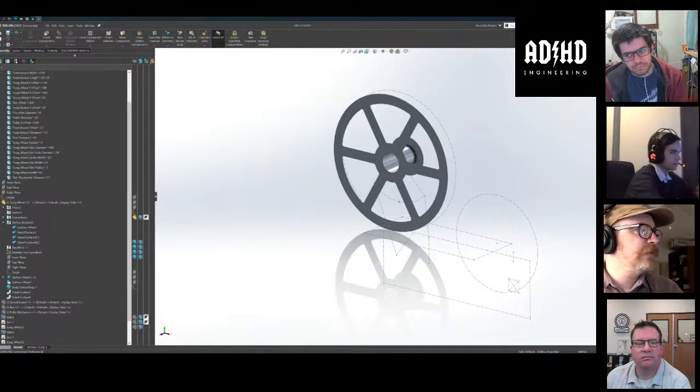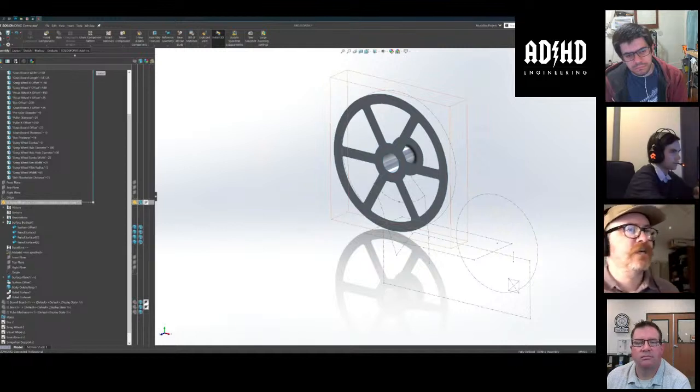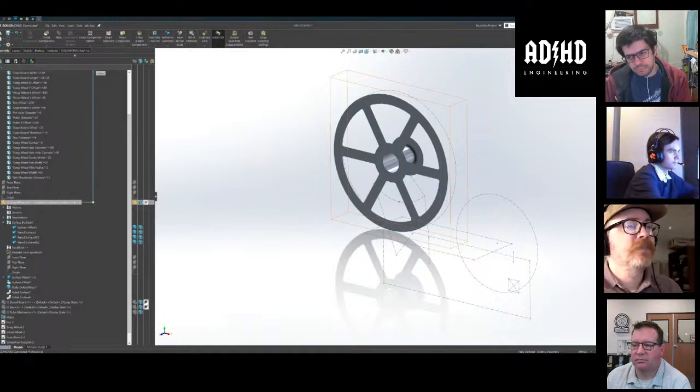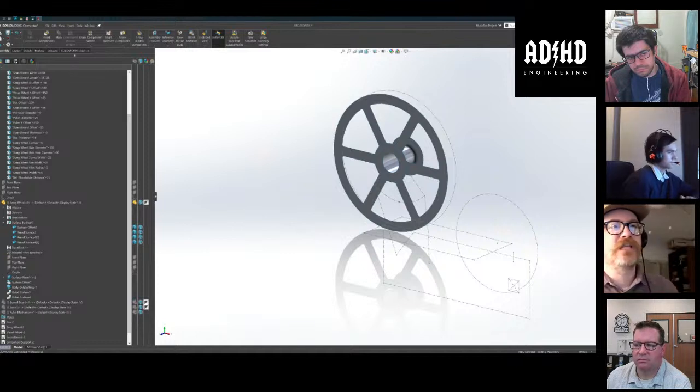So I can actually choose to edit this outside of the assembly, which I kind of recommend. One of the reasons is clutter, first of all. But second, we already have our defining position geometry. So we don't really need the assembly in order to make the part anymore, unless there are certain things we need from it.